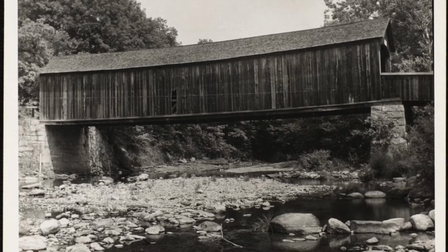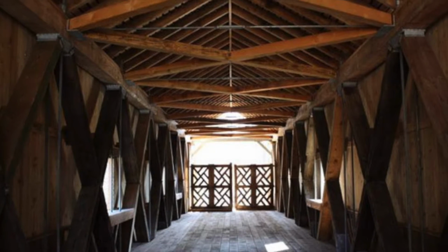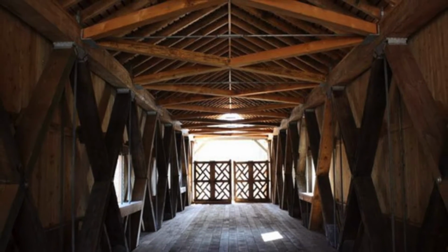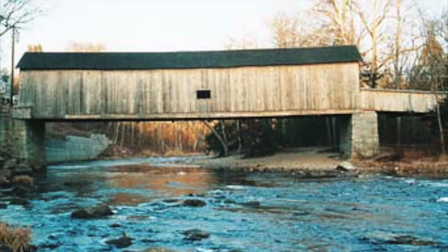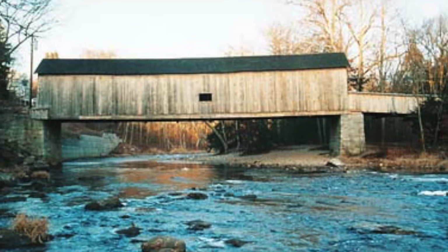It used to be a road for travel, but major restorations were made in the 1930s after a truck crashed through the floor. It is now a pedestrian bridge and has gates at either side. The bridge consists of 2 parts, one 80-foot long covered Howe truss bridge and a 30-foot span uncovered portion. The bridge has a width of 12 feet and the supporting beam is 1 foot thick. It's supported by a fixed end at one end with rollers in the middle and at the other end.